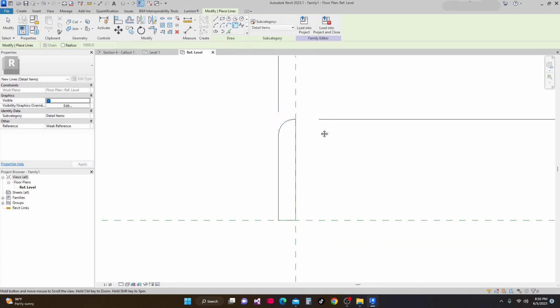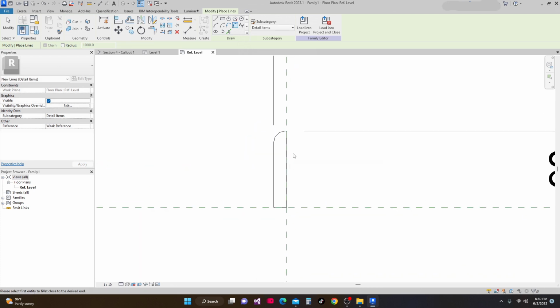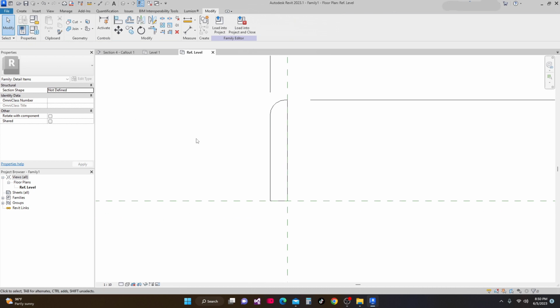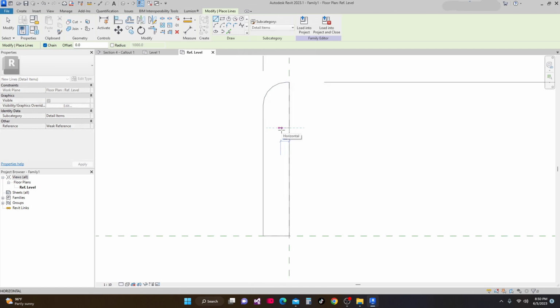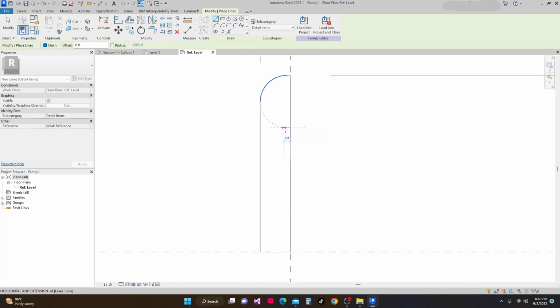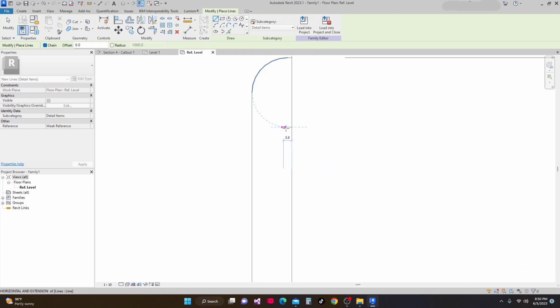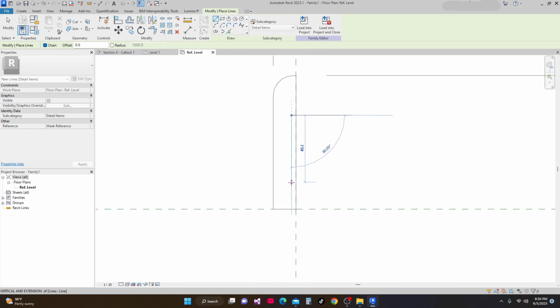There it was our fillet arc, and then next is we're going to make a line again, and then just make a line like this, small line of 5, or make it around 3 only, 3, and then down. Okay, now I'll trim this,